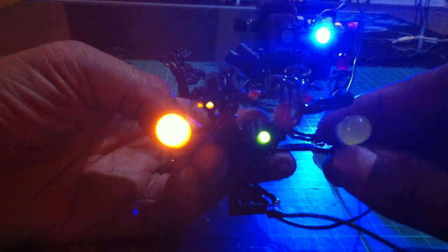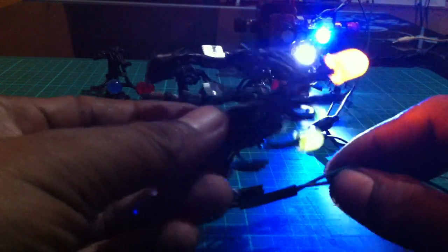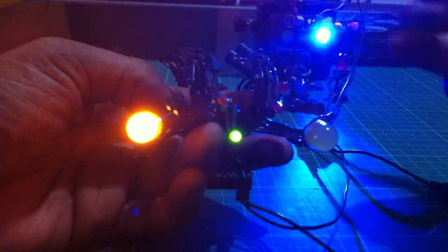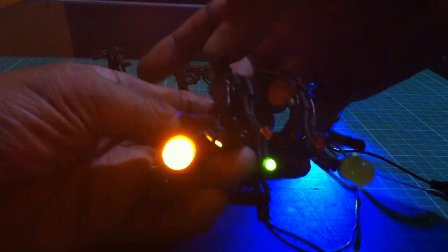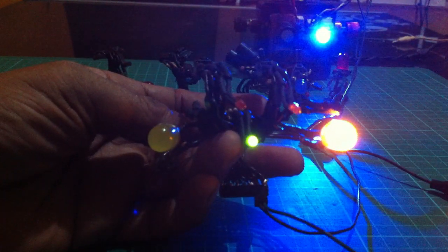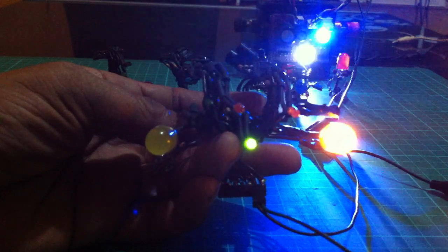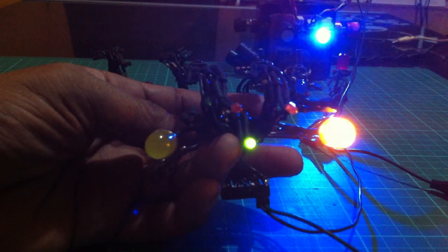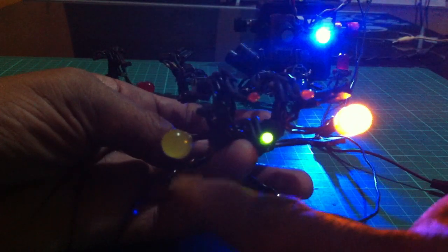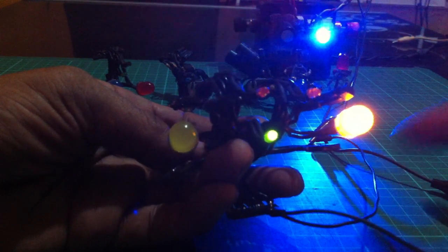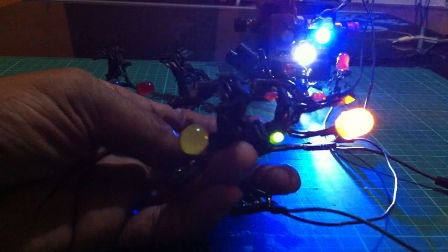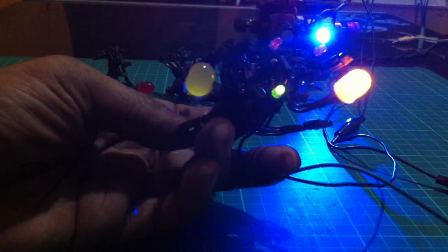This is the full build circuit of a transistor bistable multivibrator with one output LED turning on every time you push the switch. The other one, it latches. It toggles, it latches or toggles, switching to the other side of the light. That is the characteristic of a bistable multivibrator. And now, as you have seen here, the LED is fully turned off because of the PNP transistor that served as a constant current source to the circuit.